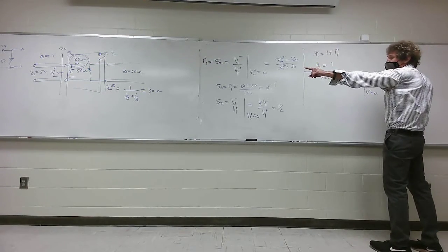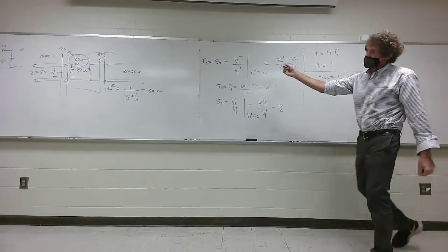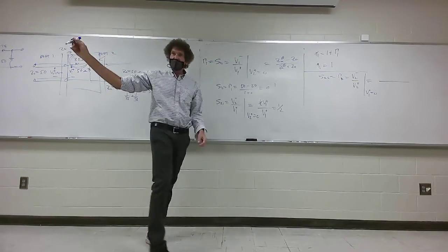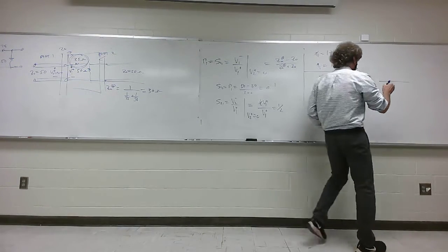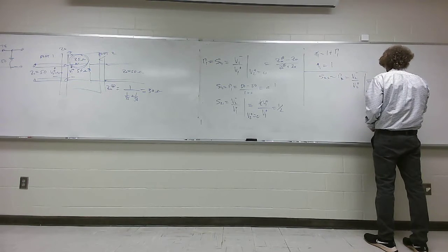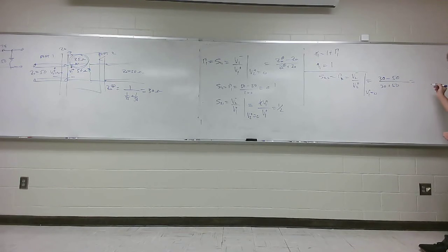What am I going into, class? How many ohms? Port 2, looking this way, we just got it. How many ohms? 30 ohms. 30, right? It's going in at 30. I came from 50 over 30 plus 50. Or here, it's going to be what? Minus 20 over 80 or minus 1/4. Do y'all agree with that?